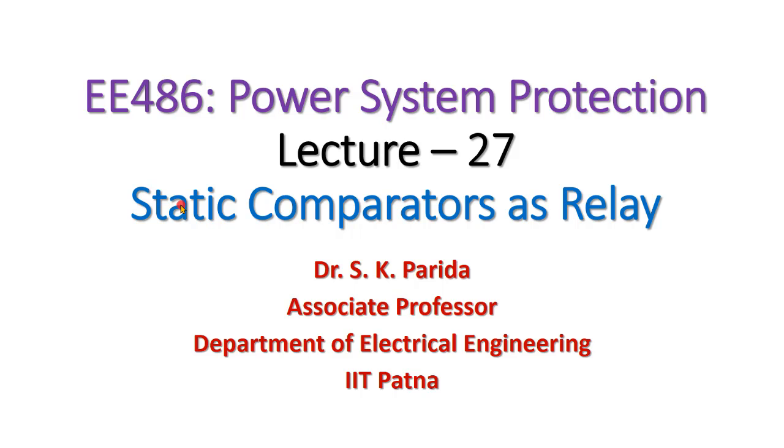We have two types of static comparators available with us, that is amplitude comparator and phase comparator, and we saw the duality between these two comparators, how one of the comparators can be used to act or function as another comparator with the same input.